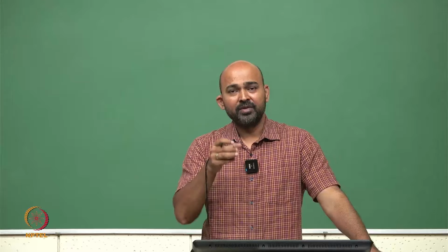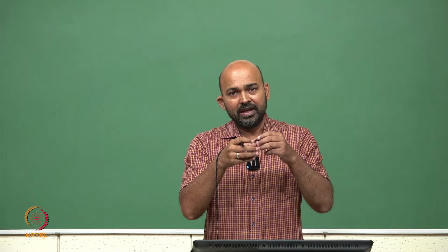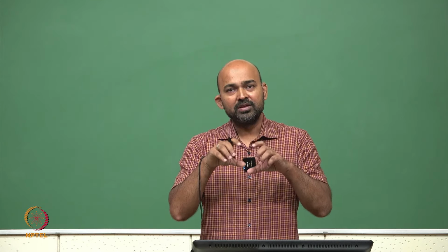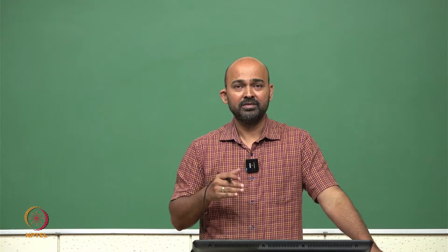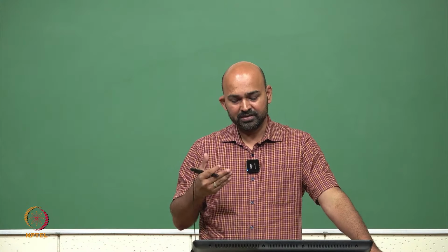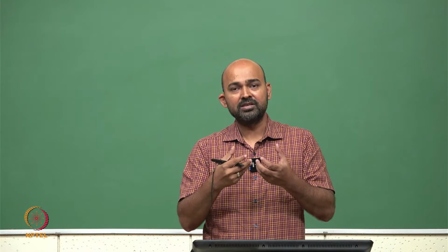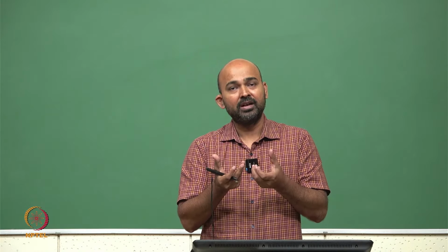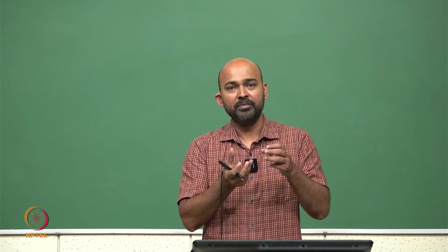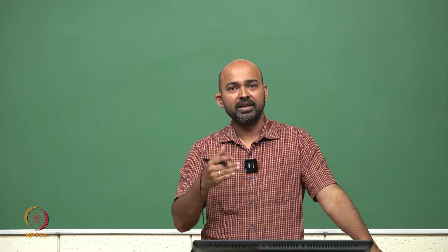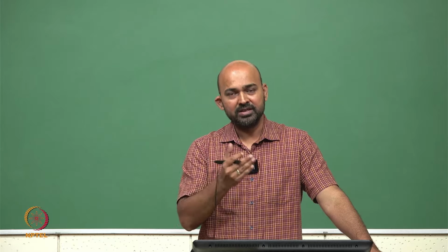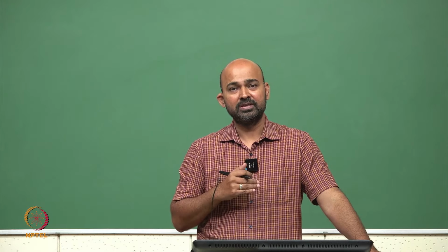When we make these vias, the extra amount of length of this via which is connected to the signal acts like a stub. A stub is an extra piece of conductor which is connected to your main conductor, and for high speed designs or high frequency signals, this extra piece of metal acts like a small antenna sort of thing.